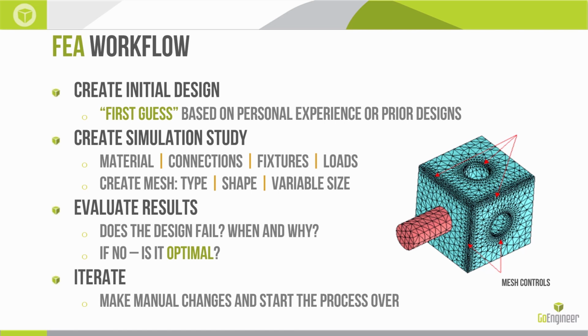And the reason we do that is because those are areas of concern. Those might be places where we suspect there could be stress concentrations. They might be areas where we are incorporating a press fit or a bearing. But we don't want to mesh the entire model that size, because it would just take an inordinate amount of time and kind of unnecessary resolution.